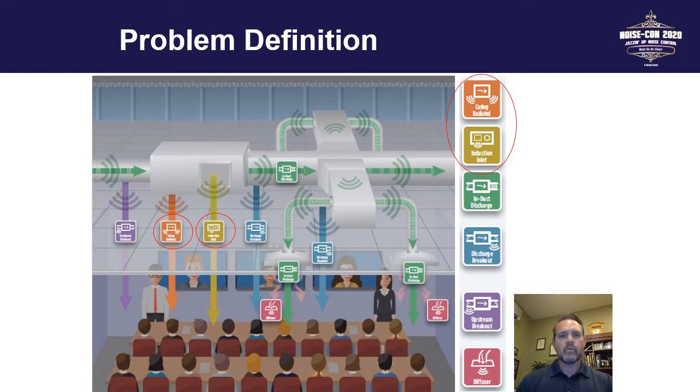So specifically today, though, we're going to put a focus on the casing radiated and the induction inlet, which I've circled in red. And just real quickly, there are some common treatments that you commonly see in the field. Things like field lagging wraps around a unit. I've seen gypsum board enclosures around units. I've seen the use of increased mass in ceiling tiles, whether that's in the tile itself or some materials above the tile to help address noise. Silencers, lined ductwork.